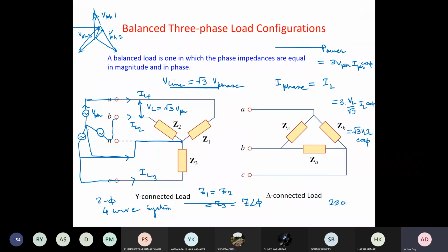So the neutral point balances the potential difference. Here, because of this fourth wire, this point will be at zero potential, and you get the same phase voltage for each and every phase from the supply point of view. Okay, because we don't know, for one house there will be one load demand, and that is also variable. For another house there is a different load demand. So say you are supplying three houses from three sources, three phases, then there is a high possibility of unbalanced load. So then we should always use the neutral.